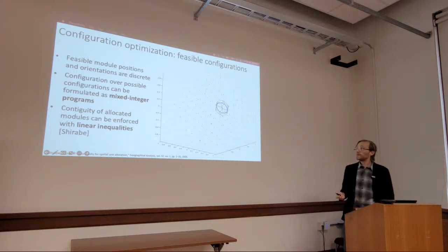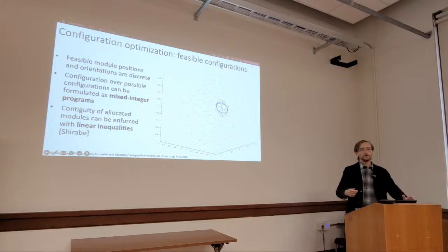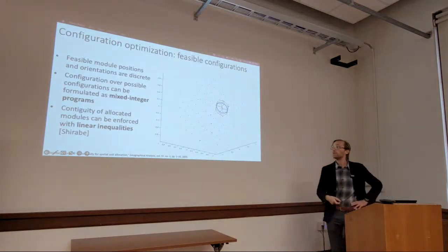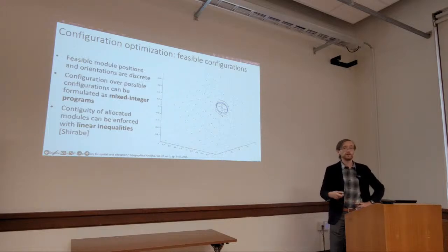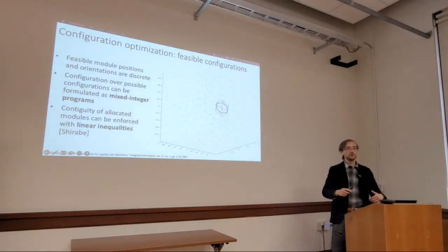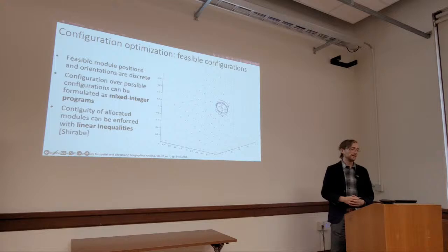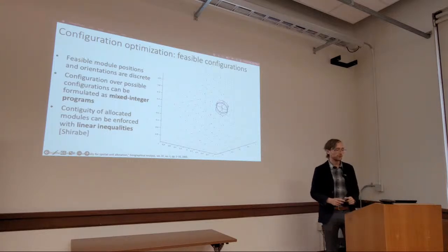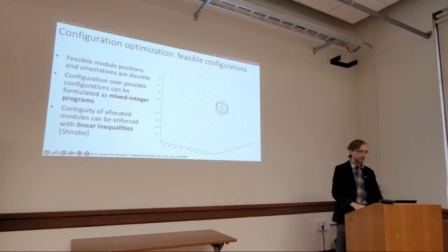And that means that if we want to optimize for an arbitrary configuration, and let's say optimize for the stiffest configuration with some constraints maybe on the achievable thrust and moments, we end up with a mixed integer convex program. A mixed integer convex program is a program where we start with a convex program, and then we have some variables that are actually integers. So it's not convex anymore, but there are still methods to solve this program pretty efficiently depending on the structure of the program. Still not as efficiently as a convex program, but not bad at all.